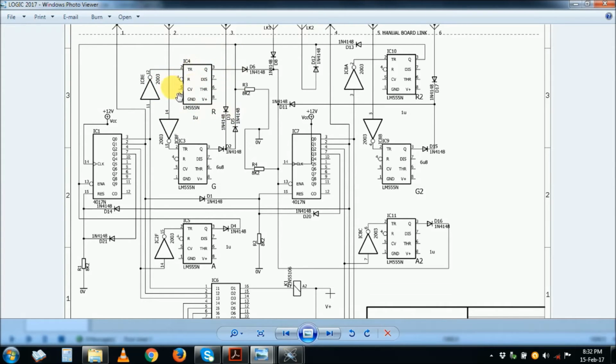Remember our simulation. Here I've just indicated the capacitor values that you put in. These are the values for the capacitors for different circuits, because these timers now represent the lights themselves. So the top one, IC4, is actually the red output. Then the middle one is for the green light. The bottom one is for the amber light. The same with the IC4017, the counter: the first output is for the red, the second one is for the green, and the fourth one is for the amber.